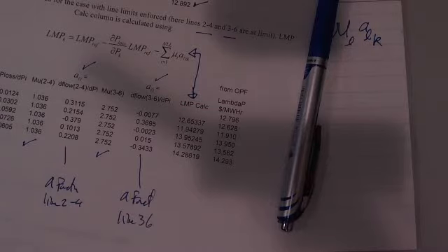There's also lambdas that come off of the constraints, the mu factors. The mu, if you study optimization, it simply says that's going to be the change in cost if I relax the constraint by, in our case, 1 megawatt.